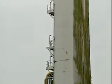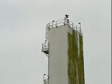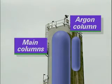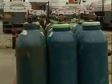Argon is separated as a byproduct from the oxygen-rich liquid, in a side column by further fractional distillation. Small quantities of gases can be supplied to customers in cylinders. Larger quantities of air products are supplied as liquids in refrigerated tankers.